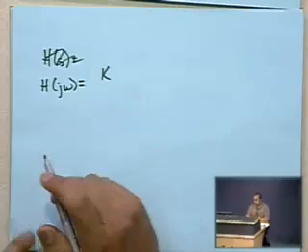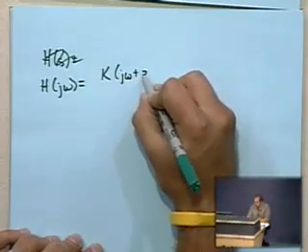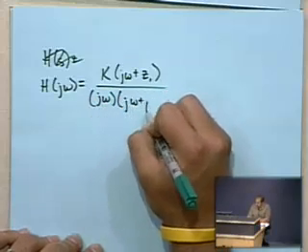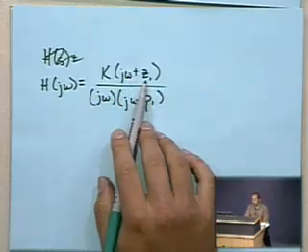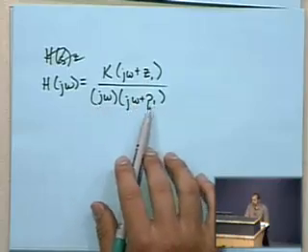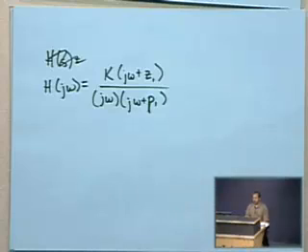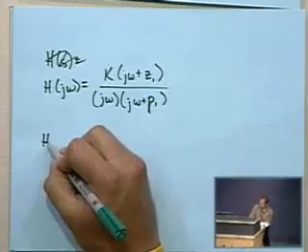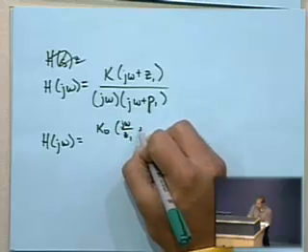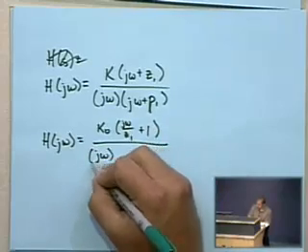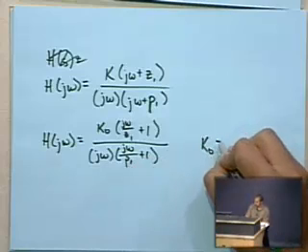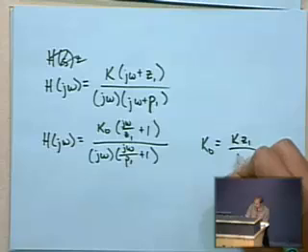So you have some constant k, and then a form where you've got j omega plus some zero frequency z1. This is one of those zeros at the origin that we just talked about, and this is a pole at some other break frequency p1. When we write that in standard form, H of j omega equals k0 times j omega over z1 plus 1, and j omega over p1 plus 1. And in this case, that value k0 will equal k times z1 over p1.